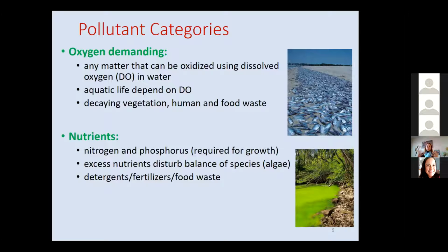When algae is blooming, it creates already issues with aesthetic conditions. They release taste and odor compounds. Some algae, hazardous algae, release toxins. And when they die and decompose, they act like oxygen demanding material. So it's a lose-lose situation. And the nutrients mainly come from the detergents we use, fertilizers applied onto the agricultural land, and any other food waste.